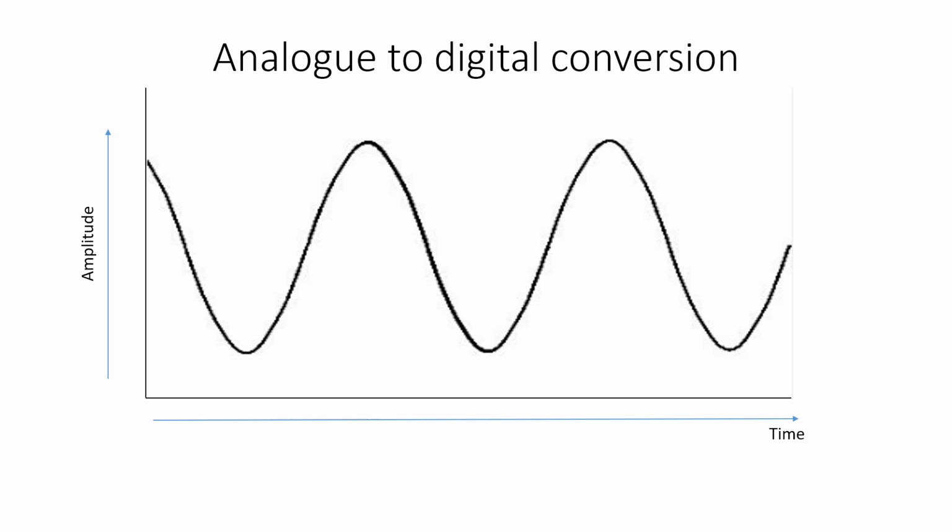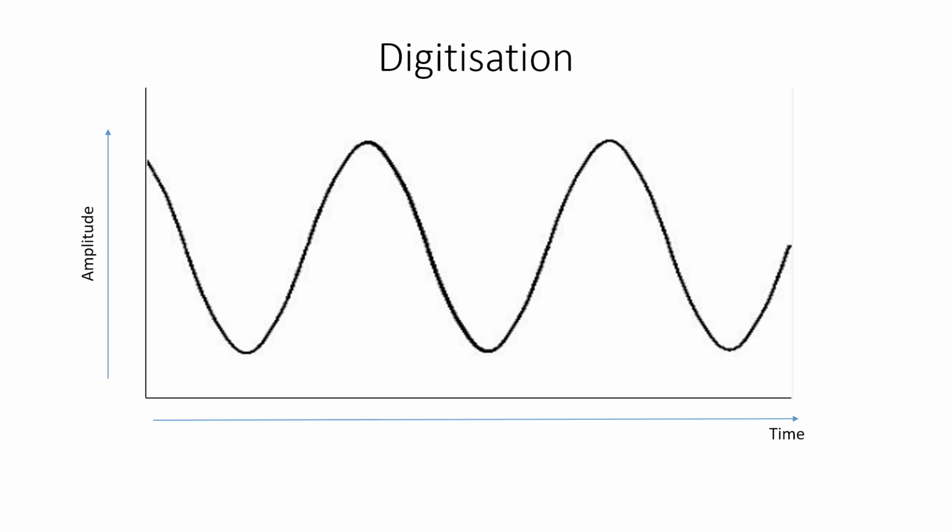This shows a simple example of an analog signal varying in amplitude over time. The analog signal is converted to a digital signal by measuring the value of the analog signal, which could be a video or audio waveform, at regular intervals. In order to convert the analog signal into the digital domain, it's measured periodically at the sampling frequency, with the sample values being stored as binary numbers.